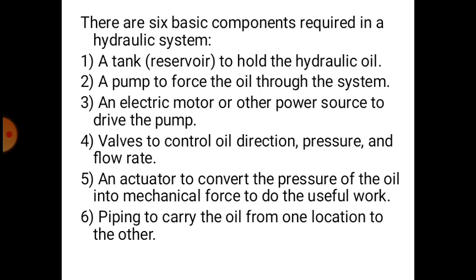There are 6 basic components required in a hydraulic system: a tank or reservoir to hold the hydraulic oil, a pump to force the oil through the system, an electric motor or other power source to drive the pump, valves to control oil direction, pressure and flow rate, and an actuator to convert the pressure of the oil into mechanical force to do the useful work.